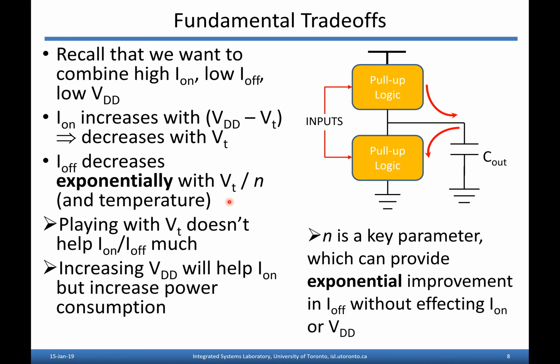And in a sense, we can always trade off on current and off current as designers just by making the transistor bigger and smaller anyway. So that's not really very exciting. So what a designer of technology really thinks about, if they're trying to make a better switch, is to improve this ratio of I_on over I_off, right? If you improve that ratio, then you've really done something, right?